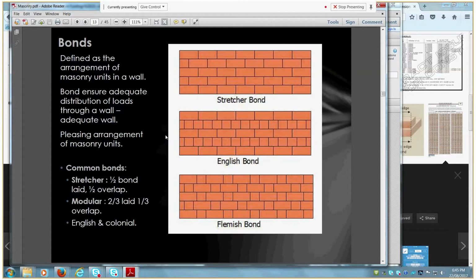I don't know, did you have the floor slab replaced as well? Eventually we did get everything. Right, so just a clean slate. Yeah. If you had a scenario where they were using the same footings, typically you probably wouldn't be able to use those same footings again to do double brick or cavity masonry. Or if they're putting in new footings, possibly it's going to be far too expensive to do the double brick or the cavity brick, because of the cost of labour to produce, but also the cost of footings.